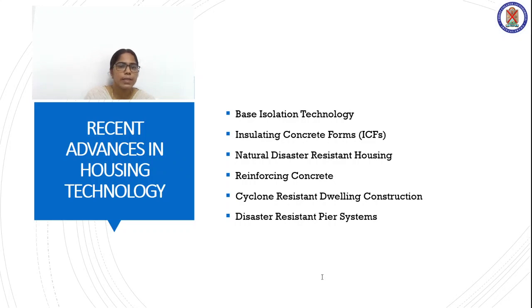Reducing the forces transmitted to the building from the ground by placing the building on top of a mechanical system of isolators, sliders and dampers is called base isolation technology. This dampens the violent movement of the earth during the seismic event. By using isolators, the building is decoupled from the ground motion of any earthquake and the transmission of seismic energy to the building. This is done by lowering the vibrational frequency, allowing the building to move or displace.